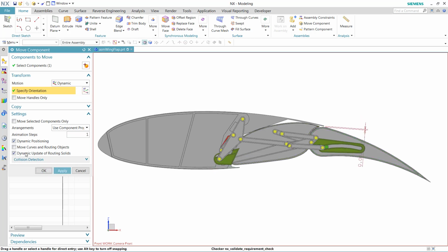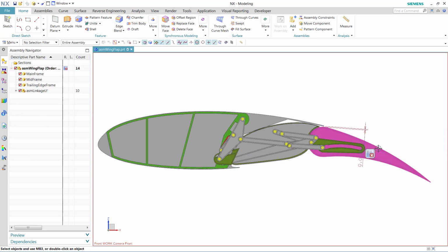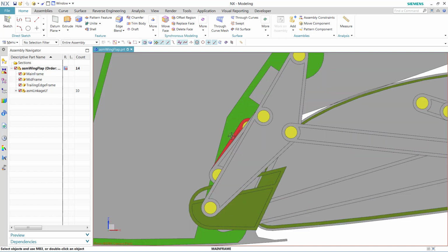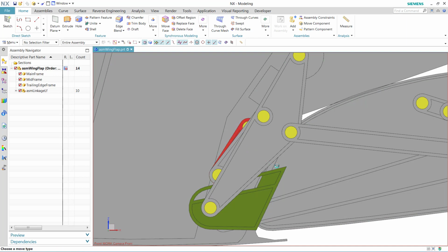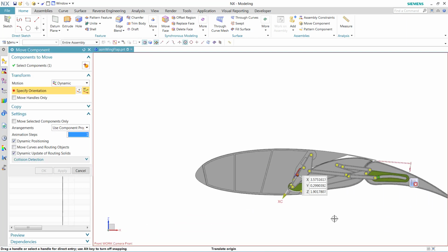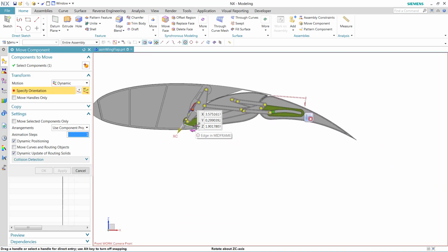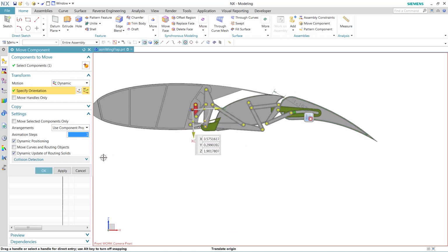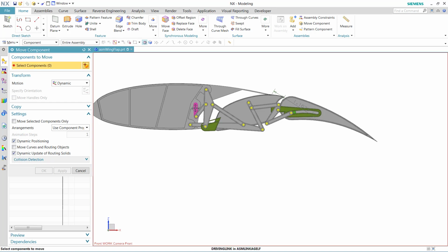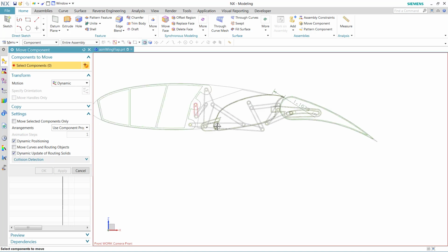Similarly, if we want to, we'll say OK there, and we'll start to see the HD3D tag appear. So we can exercise our mechanism again. As we do this, we come back out into the green region and press apply. We see our tag go away because we're not violating that requirement anymore.